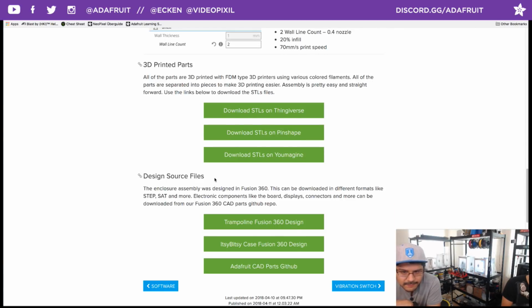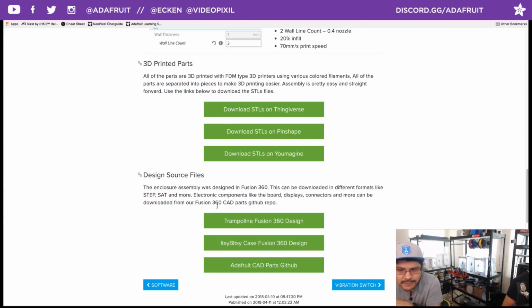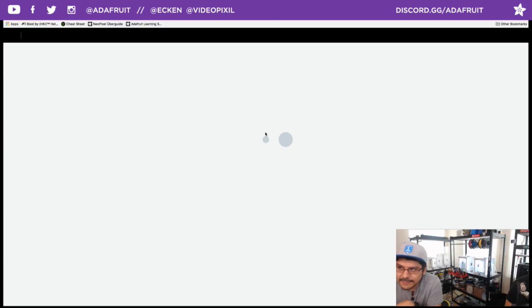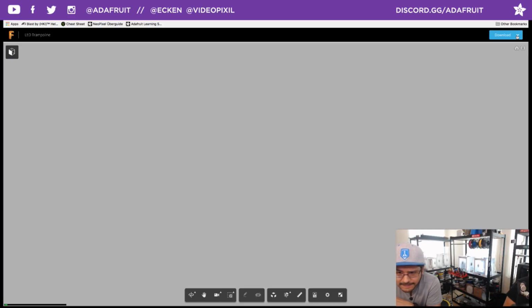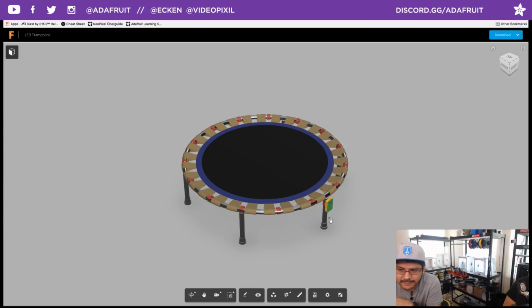STLs are fine and great, but what's even better is the source files. These are all designed in Fusion 360, so if you click on these, you can get the full source of them. You can export them out. There's a little drop-down download button that gives you an option to download in any type of format: STL, SAT, STEP. STEP is kind of the standard for solid modeling. If you're using something like Onshape, you probably want STEP, and if you're using something like Tinkercad, you probably want the STL.